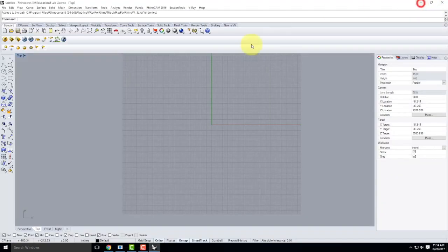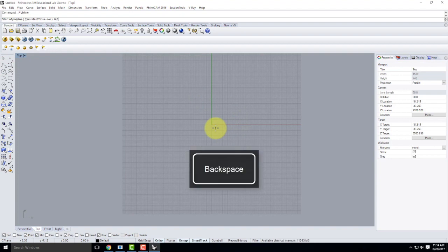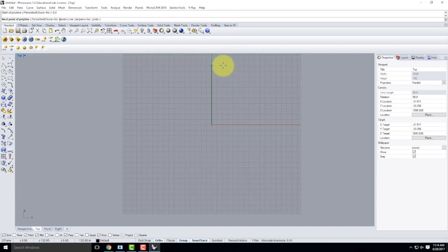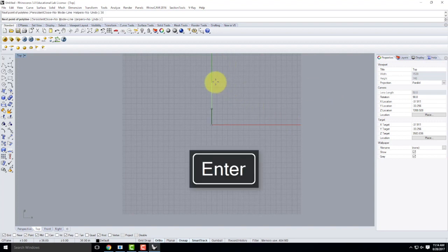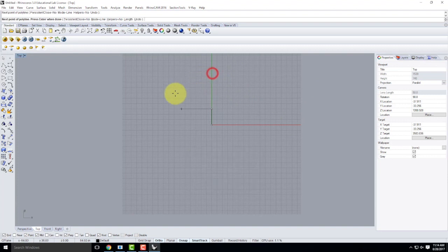And we're going to start right at the bottom corner right there as we start to draw. So I'm going to use the polyline tool, which we've used before, and I'm going to start at point 0,0. And I'm going to draw a line that's the length of one side of this bridge. So if I look at the dimensions, it's 36 inches. So I'll type 36 and then enter. Remember, our default units are in inches, so if I type 36, it's going to be 36 inches.